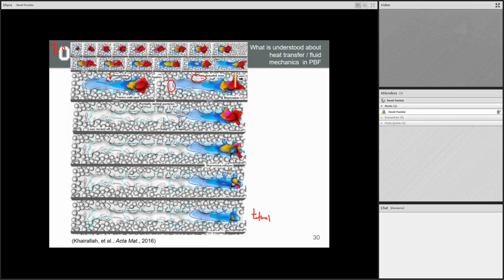You get a melt pool that is fairly smooth, but has some roughness to this. So this is on the order of just tens of microns. So if you were to feel this with your finger, you would feel a little bit of a ripple. It wouldn't be perfectly smooth like you can get from machining, but it's not too bad, right? It gets a fairly smooth surface. You get then here a pretty large depression, and then eventually this is then the laser turning off right here. This would be laser off.